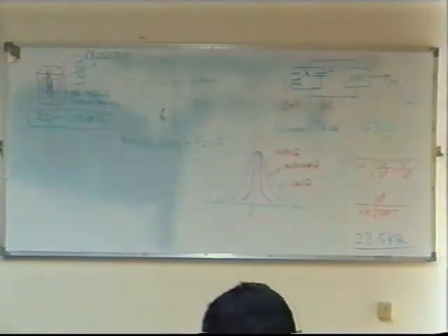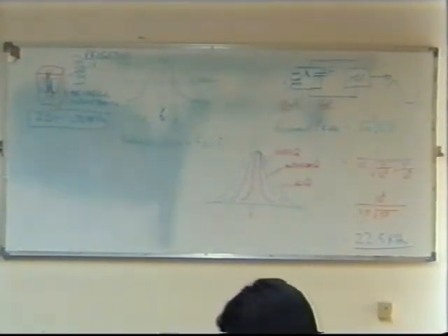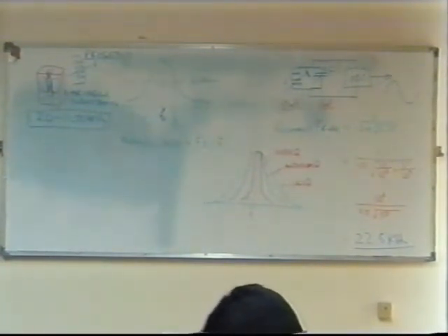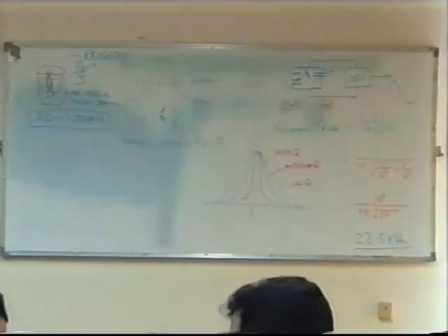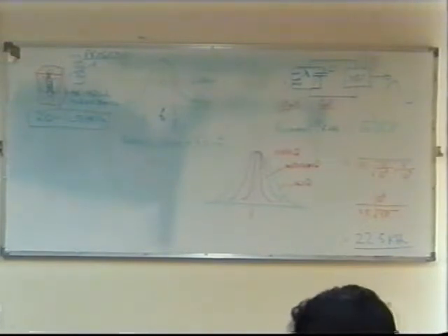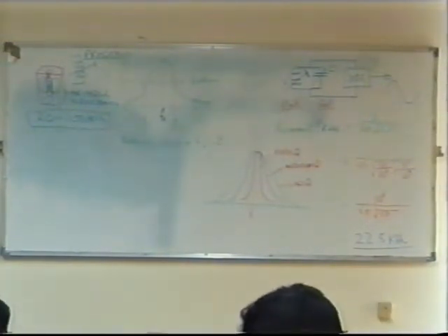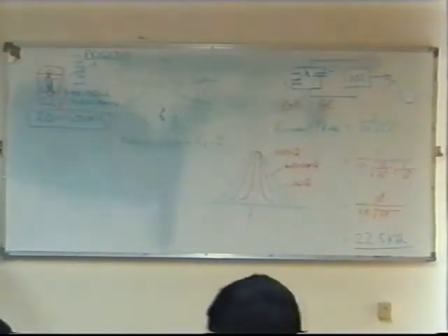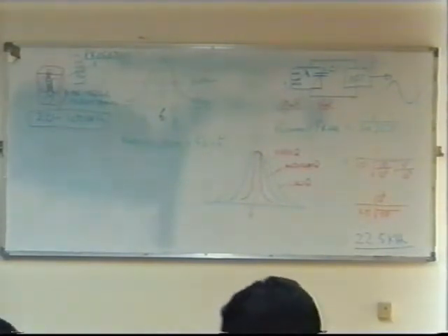And it vibrates at the radio frequency, generating a small voltage across itself. But the problem with crystals is the higher the frequency you want to generate, the smaller and the thinner the crystal. So there's a practical limit where the crystal just becomes too small and too fragile to generate the very high frequencies we need, say, for microwaves.